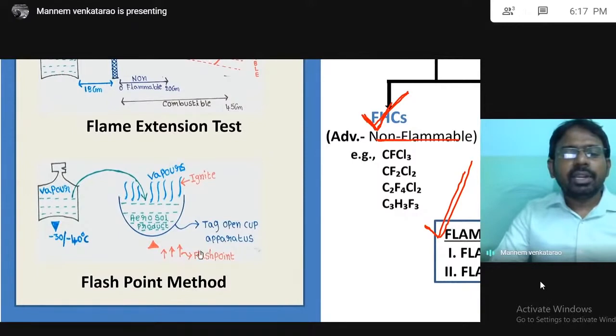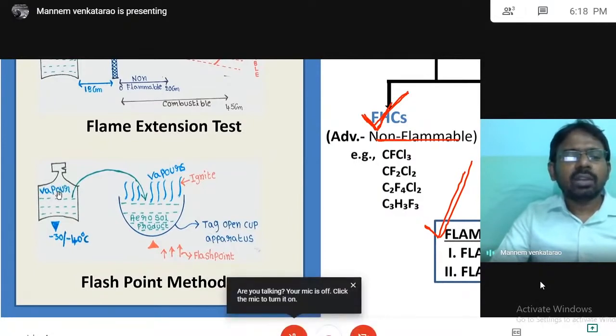So, this flash point test is performed only for the product but not the container. Why? Because in the flash point test, you increase the temperature. Once you increase the temperature inside the container, what happens? The entire propellant converts to vapor, thereby the pressure will increase. At a particular instant, the container will burst out. To avoid this, what is the problem? Why are you not opening the container? Because of pressure, which is due to the gas. First of all, you convert gas to liquid. How can you convert gas to liquid?